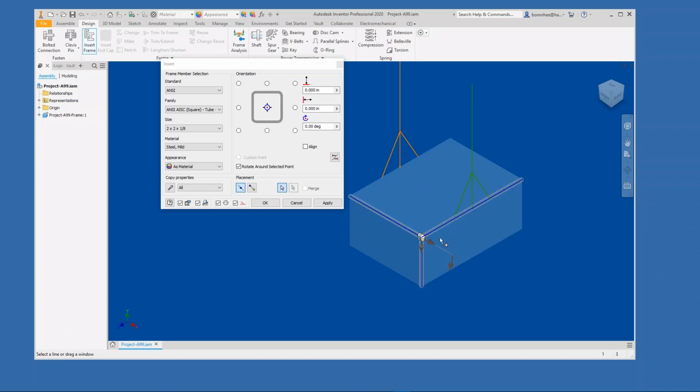The reason is, the first method I showed you, Inventor creates 12 different part files. This method, Inventor is only going to create 3 part files because this long member is used 4 times in here, right? And I guess it depends on how your company handles the cuts and the stock numbering, the part numbering in your inventory.